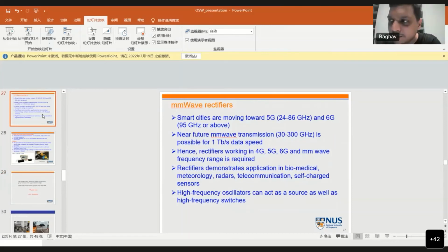Okay, so basically we observe this in our simulation also. When we apply very high RF power to these spin diodes, typically the precession angle increases. But when we increase the power a lot, the precession angle does not increase in that ratio. So when we keep increasing the RF power, their voltage will go up, but not in that ratio, so their sensitivity will go down. And of course, above a certain power they cannot work and your MTJ will break down because of high current.